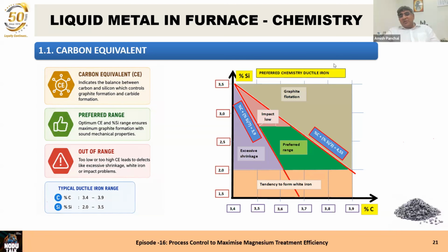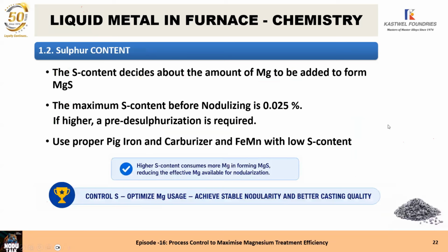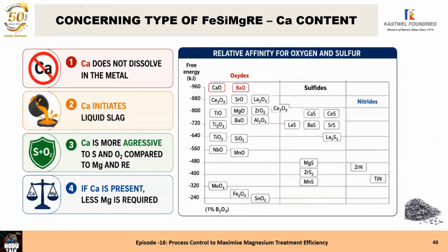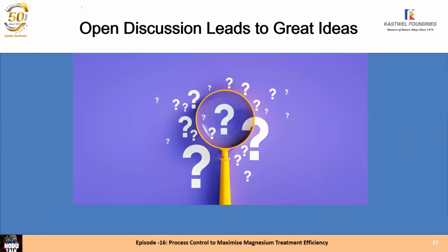Okay, sir. Now we go to another question. Mr. Jitendra Shiani is asking, when the tensile test bar is broken, the appearance of the breaking surface is half white and half black. What is the reason behind this? Mr. Bazutkar, can you start answering? Well, when you break the tensile bar and look at the fractured surface, it reflects light. It depends upon the matrix present in the tensile bar: ferritic matrix, pearlitic matrix, or a combined matrix. The combined matrix will give you a black and white fracture. The ferritic matrix will give you a white fracture, and the pearlitic matrix will give you a black fracture.